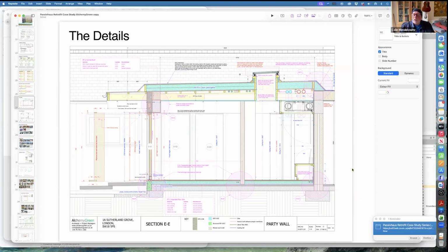Gary Kelly asked the question which we answered, did we undertake a blower door test? And we said, no, not worth it beforehand. But obviously we did afterwards. I've got loads of pictures of wandering around site with a smoke device, finding which way the wind was blowing. We found all the leaks and we fixed them.